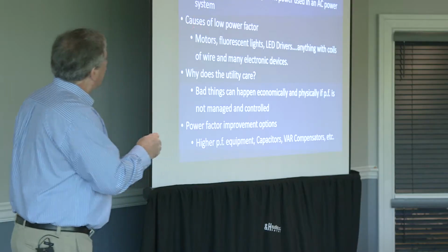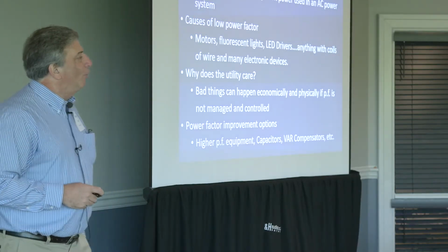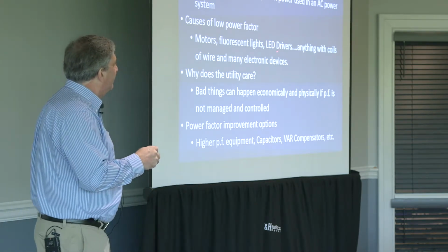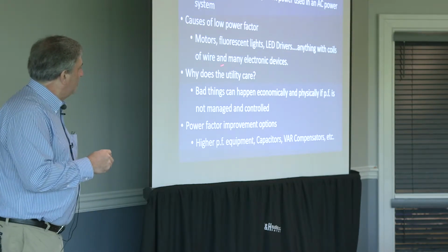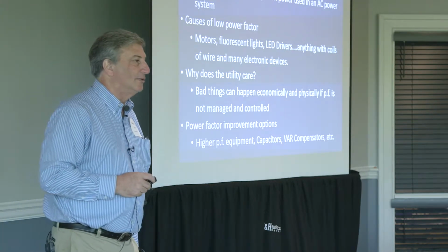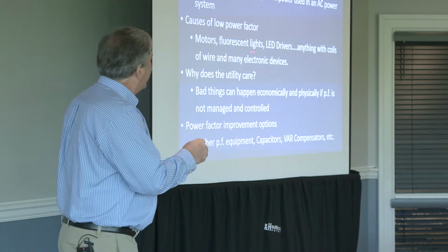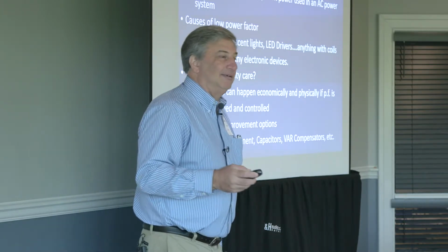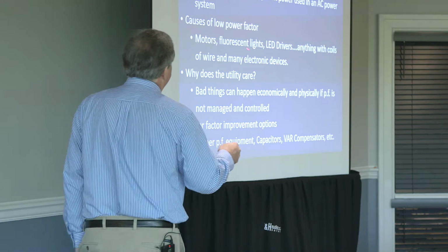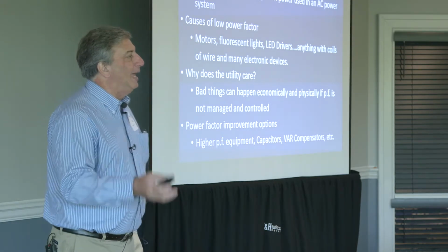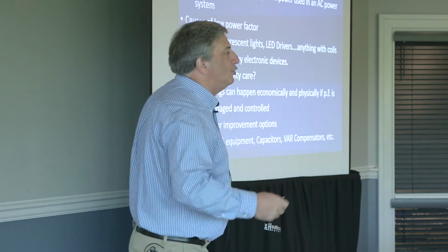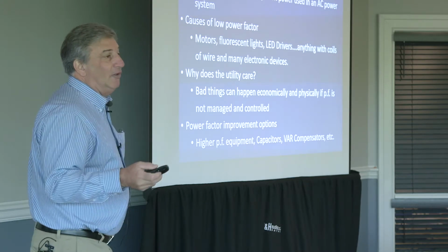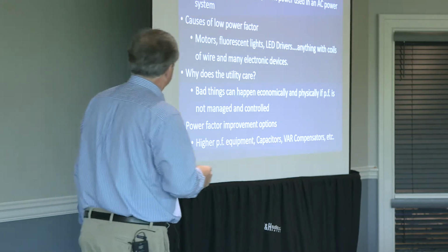That's important. Causes of low power factor. When we talk about managing power factor, we're really looking at motors, fluorescent lights, and LED drivers, or anything else with coils of wire and many electronic devices. How many of you have any of those in your plant? Yeah, they're a fact of life, right? The range of power factors in the market when you buy equipment is huge. So if I'm not looking, I might get really low power factor stuff that's a pretty good deal, and it could even have reputable brands on it.